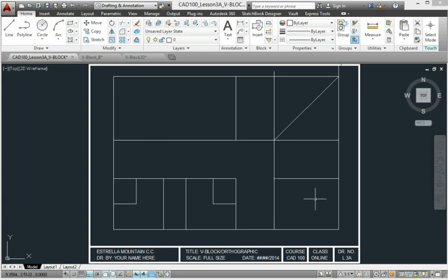The top view and the right side view are going to be projected from the lines we have already drawn in the front view. So you could take these lines, grab these grips, and stretch them across. Hit the escape key, grab another grip, stretch it across. As for here, we only need to go to this point where the top view of this block will end its location of the line. Over here we'll extend these lines across to the right side view. And there's nothing else we can project at this time.